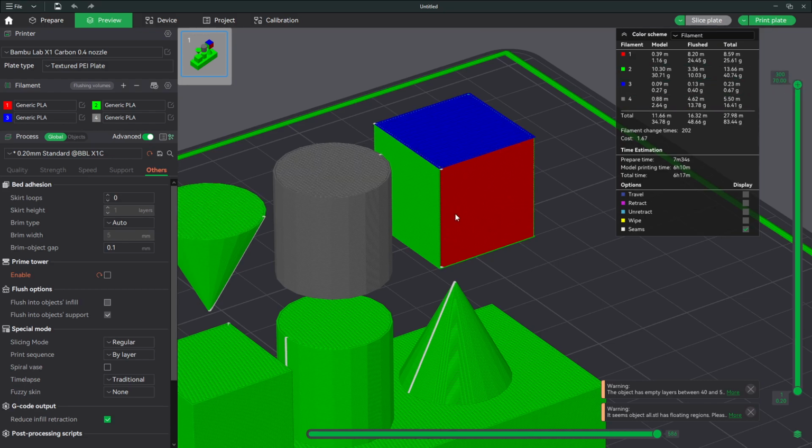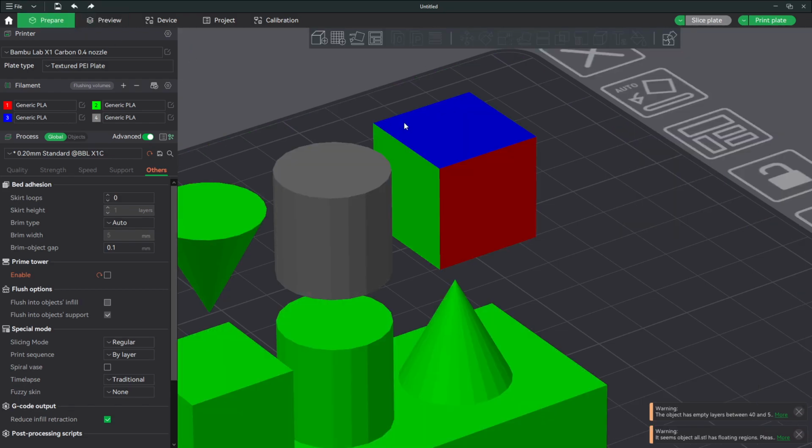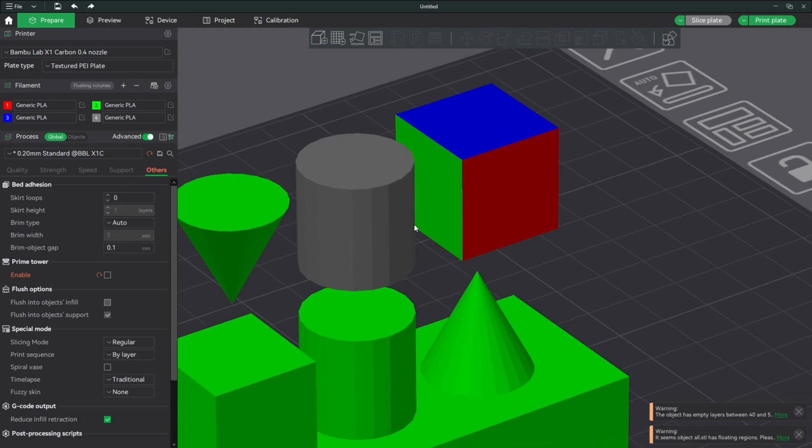That can have an effect if you're working with translucent materials, like if you're working with a thin layer of white and you're trying to put some black text on it or something. If it were to try and cut through like that red did, that will show up fairly significantly. So by using the painting tool, you really don't have control over the depth of how far that color goes. It does it based on geometry, and you're just kind of at the whims of the software as to how it's going to do that.